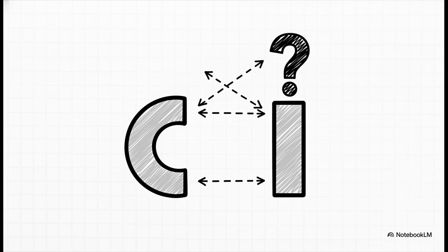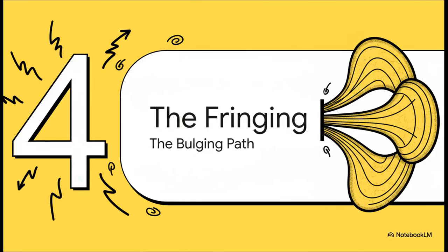But leakage isn't our only problem. There's another strange little effect we have to think about, and it happens right here, in the air gap between two parts of a magnetic core. This effect is called fringing. Just try to imagine the flux lines being forced to leave the comfort of that metal core. As they have to jump across the air gap, they don't just travel in a perfectly straight line. They actually repel each other and bulge outwards, kind of spreading into the space around them.